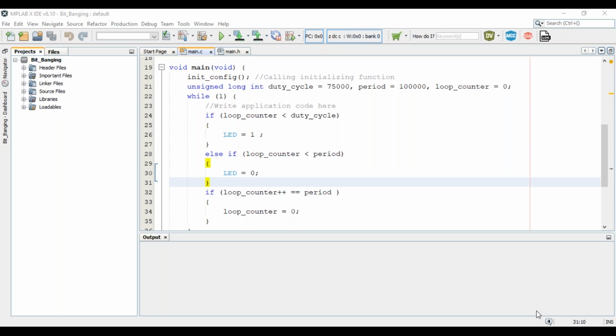Yes, I always have to keep the frequency high. You should get more pulses generated, more cycles in a given amount of time. So you keep the frequency high to make sure the load feels as if the average power is being delivered in a continuous manner.